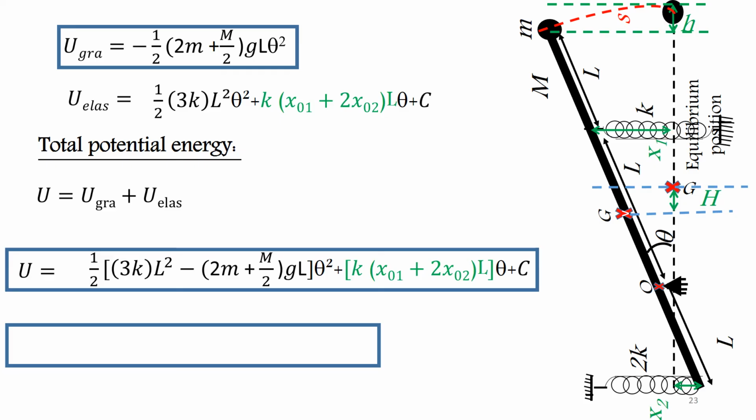And same thing, in this L theta, you see that now the masses enter in theta square, because when we have the vertical equilibrium position, the masses are useful to oscillating. Okay, it's different, and we use the same thing, quadratic form, by using the equilibrium condition, and we can cancel this term of theta, and we get this expression of U. And thank you for your attention.